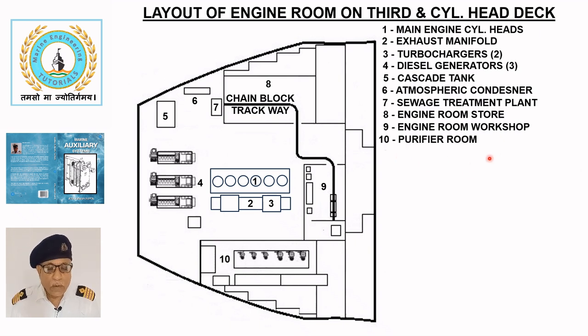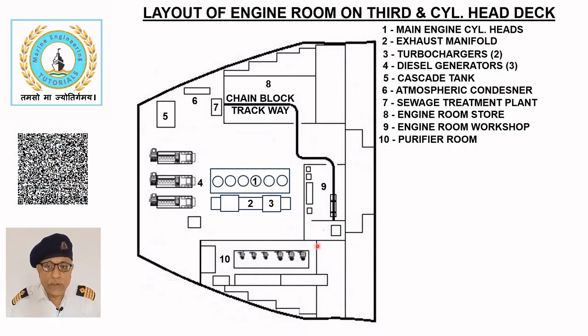Purifier room. The purifier room 10 is equipped with purifiers and fuel pumps, making it highly prone to fire due to presence of oily vapors at high temperatures. The room is enclosed and fitted with an exhaust fan to remove these vapors. The purifier room contains the following machinery: auxiliary engine, lube purifier, and heater.